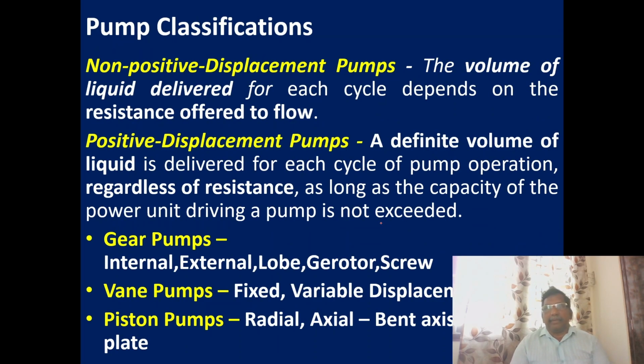What are the different types of pumps? Initially we can classify them into non-positive displacement pumps and positive displacement pumps. Non-positive means the volume of liquid delivered for each cycle depends upon the resistance to flow at the output. So if you stop the flow, it won't create any delivery. So no need to have an outlet for whatever we are getting as input.